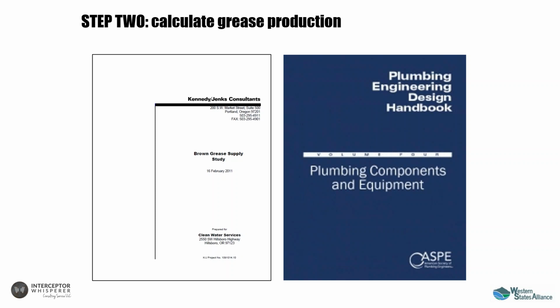Chapter 8 of this governs grease interceptors. Max Weiss, who is the director of the Plumbing and Drainage Institute, and I combined to edit this for the 2016-2017 edition. Max didn't necessarily agree with all that happened here, but we introduced something that hadn't been used before, called grease production. Grease interceptors are certified not only to a flow rate, but to a capacity. Those manufacturers that certify to a higher capacity can distinguish themselves with that capacity, and that has real value for an owner or an end user.